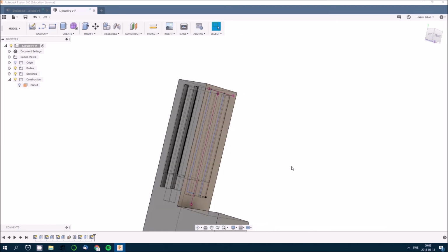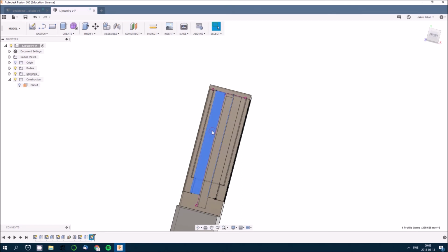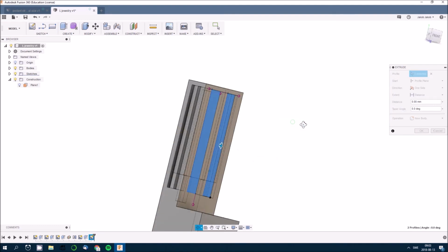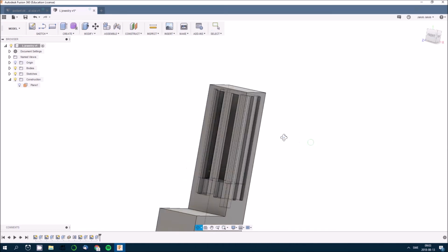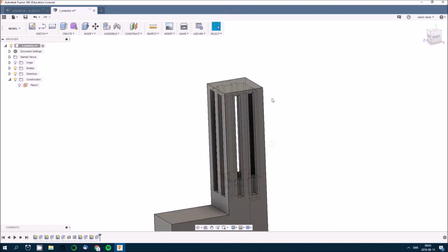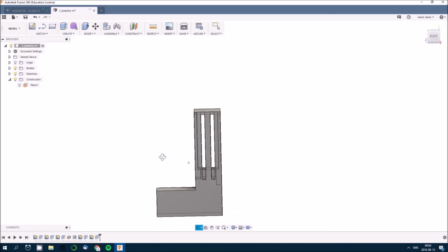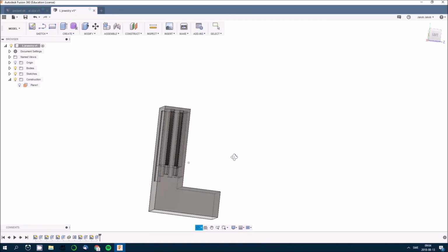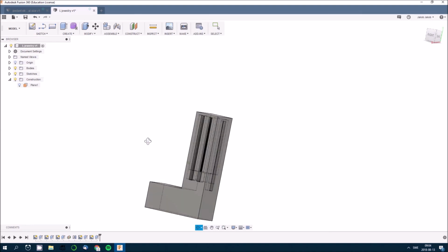Stop sketch and pick. We can actually just pick it there, and we take -4 millimeters, cut. Then we have a nice little cage for the L, and we have something to put the chain for our pendant. I think we are finished with the cage.